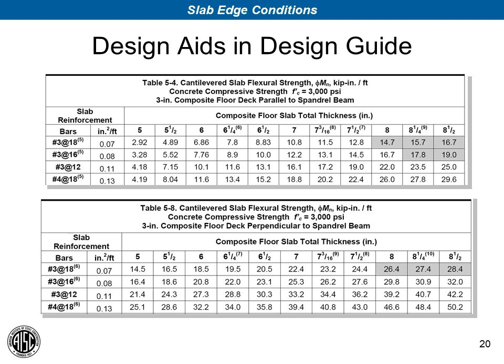You'll notice also that we're not listing welded wire fabric as reinforcement in the slab. We generally prefer using deformed bar or bar mats in slab rather than welded wire fabric, because we found that welded wire fabric can easily be damaged during construction by people walking over it, and so it gets deformed easily, and it also gets pushed down toward the deck, where it does little good in resisting the negative moment that we have over the spandrel beam, excuse me. So we really prefer using deformed bar in this case and making sure that bar is placed near the top of the slab to help us resist the negative moment.